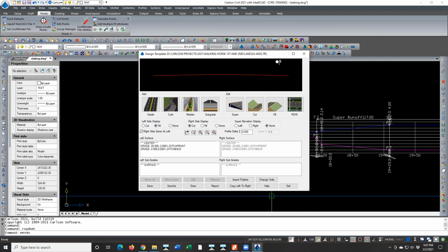Now, do you ever need to do anything at all with the top, with the multiple strata underneath? Like you need to compute how much gravel and all that, or is your job at this point done when you stake the subgrade? No, I stake subgrade and then I will have to stake top of the ballast, then top of rock, and then top of base rock. So we have a foot of ballast, 6 inches of rock, 4 inches of rock. So I slope stake it, then I stake subgrade, then I stake top of ballast, then I stake top of rock.